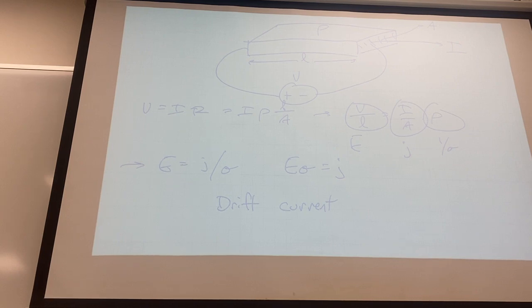They have a big pile of holes in one corner of the semiconductor and none in the other because of some steady state issue, or you've just taken a p-type and n-type material and stuck them together, and there's a lot of holes on one side, a lot of electrons on the other, and you need to flow across that barrier in order to diffuse and make it so there's kind of an equal number everywhere. That moment is diffusion current.